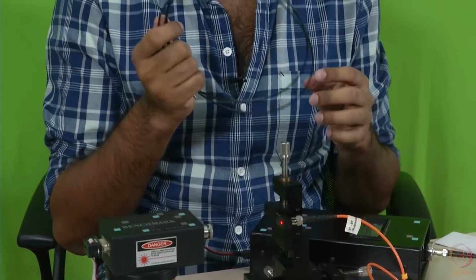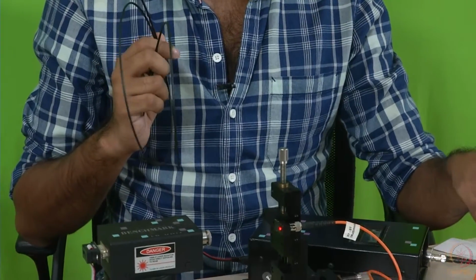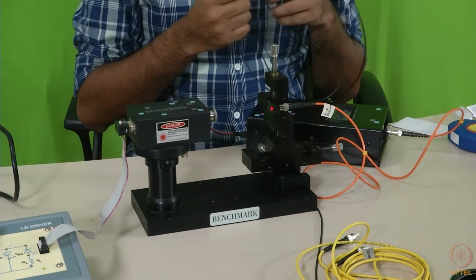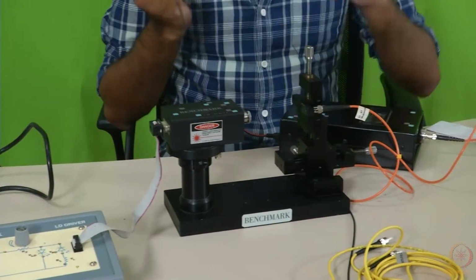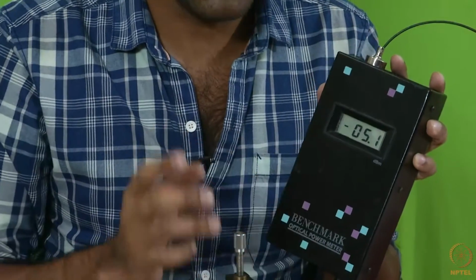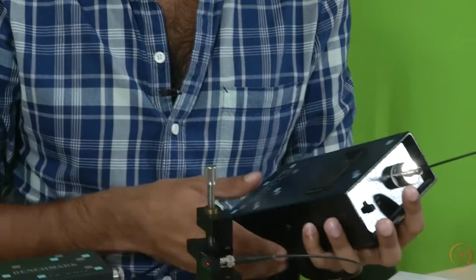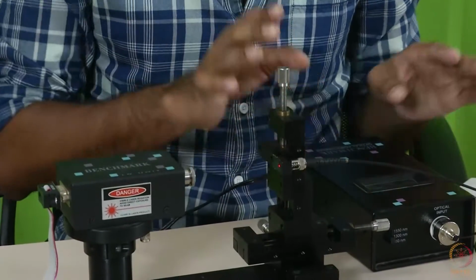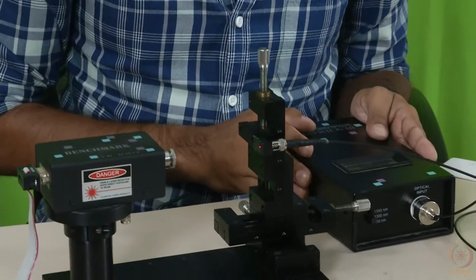So this is the black plastic optical fiber. It has a much higher core diameter than this orange fiber. You just see how much extra power it is able to couple into the optical fiber. For that we had to reduce the intensity to minimum, replace the fiber, and the maximum power it is able to couple is almost minus 5 dBm. So that means that the bigger the core diameter, the more light you are able to couple into this optical fiber compared to the other orange optical fiber. Now that is coupling into multi-mode fiber.